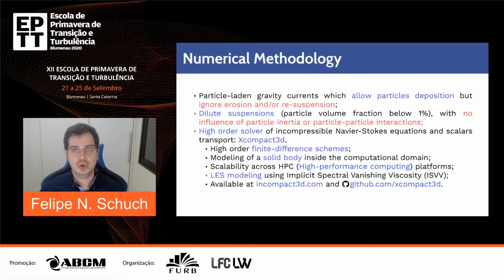Our numerical framework allows particle deposition but ignores erosion and resuspension. We assume dilute suspension with no influence of particle inertia or particle-to-particle interactions. And we use the high-order Navier-Stokes solver Xcompact3d. It is based on high-order finite-difference schemes. It can model a solid body inside the computational domain. It is highly scalable across high-performance computing platforms. And there is LES modeling using implicit spectral vanishing viscosity. And it's open source and available on its GitHub page.